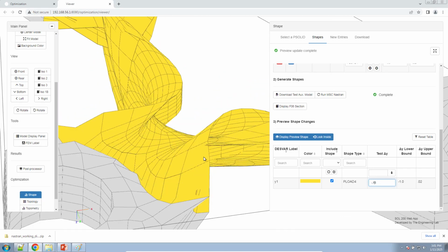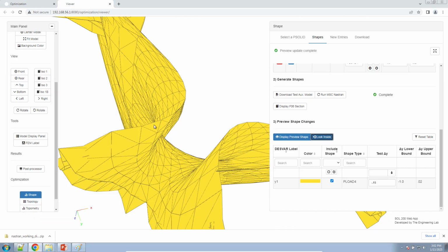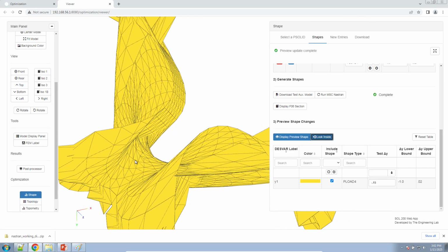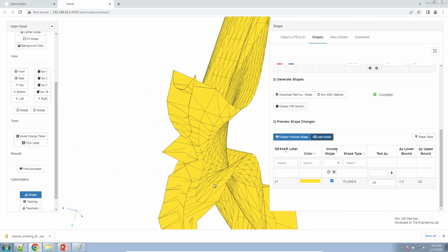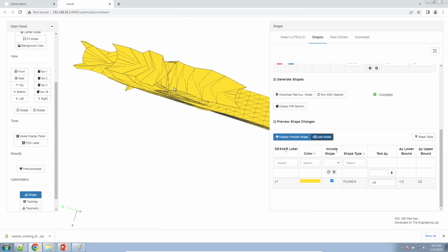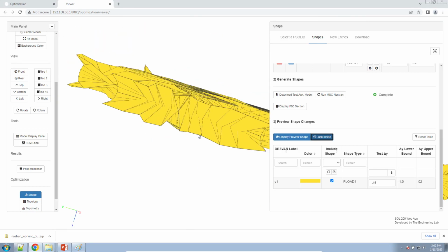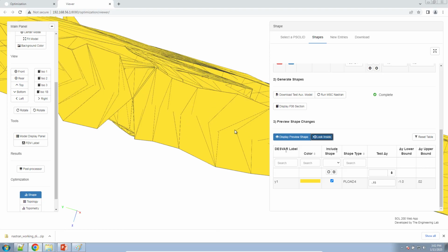And if you look here, and let's look inside, from the outside, we know we distorted the mesh. Look at all these elements that are going through each other. This is going to fail during the shape optimization. When you try and look inside of this, you can no longer look inside. So that's how you would use the look inside option.